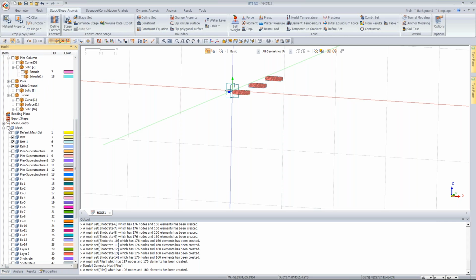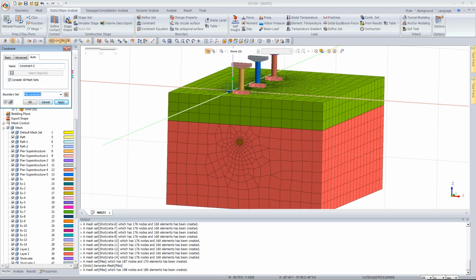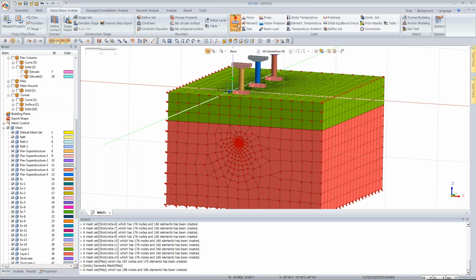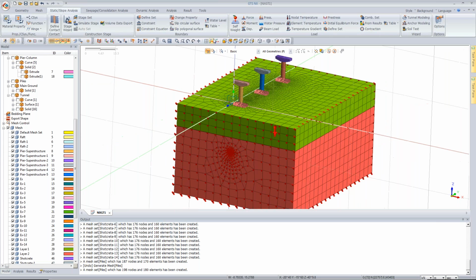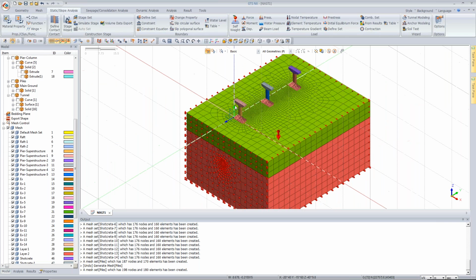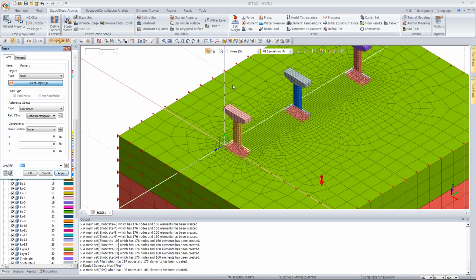Now we have the general support condition. So constraint, you can go to auto, name it as GS, standing for ground support, just say OK. Self weight as W. Okay. Now let's suppose you want to apply some load on the bridge pier coming from the foundation. I'm taking a few nodes by select by single. Okay, so let's suppose I'm selecting 3 nodes on each of the piers.